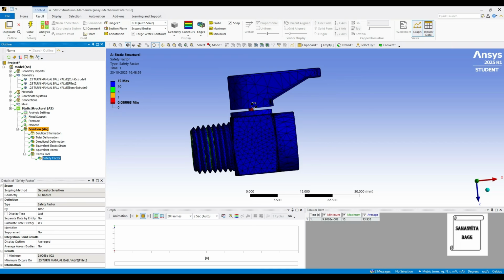You have to change, which means that if the application is known, say we are very sure that 2 megapascal is the pressure and the moment is 200 Newton mm, then you can go for brass as one of the materials and then stainless steel. But do not use plastic in this application. It cannot work because it is going to fail. So you have to be very sure as to what material has to be used where. It should be as per the application.